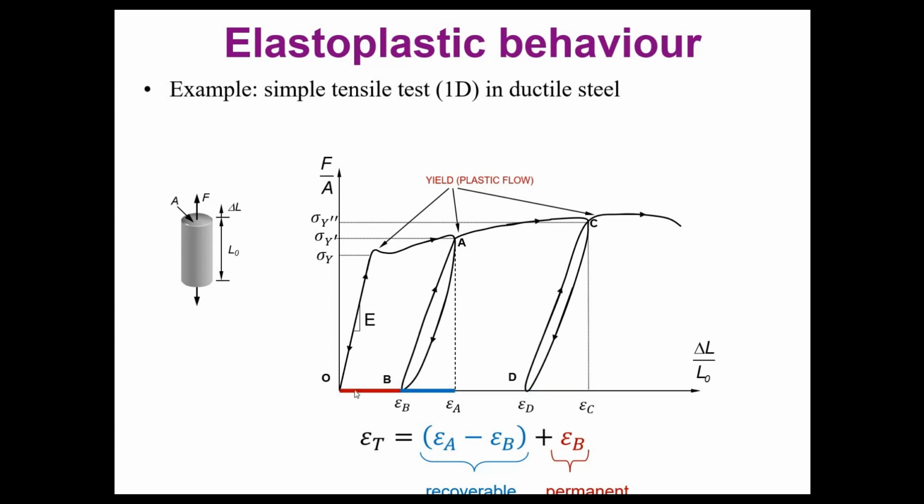In the first loop, in this example, which is not numeric but just theoretical, you have the same amount of elastic deformation as plastic deformation, but in the second cycle you notice that the plastic deformation is much bigger, and the elastic deformation that is recoverable is more or less the same as before, and actually will be approximately the same.